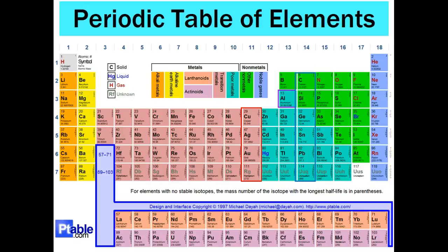Carbon is a unique atom in that it actually changes its resistance depending on how much it's compressed. The original voltage regulators were what they call carbon pile regulators. They had a big spring pushing the carbon together, and when the voltage tried to go up, a solenoid would pull them apart and cause the resistance of the carbon to go up. If the voltage tried to go down, it would go in and lower the resistance of the carbon. Carbon pile regulators are still out there. You can still research carbon pile voltage regulators.